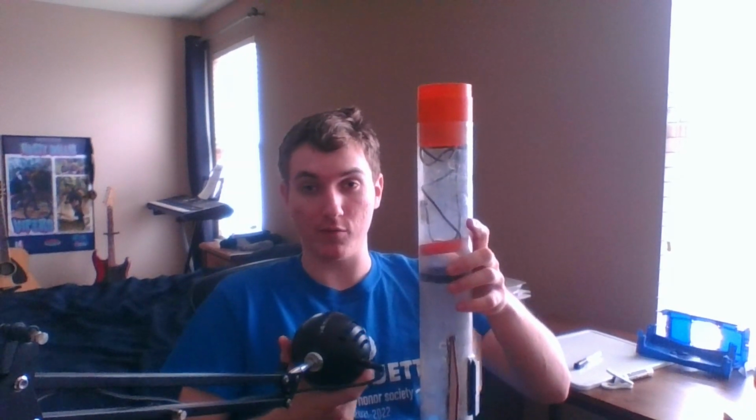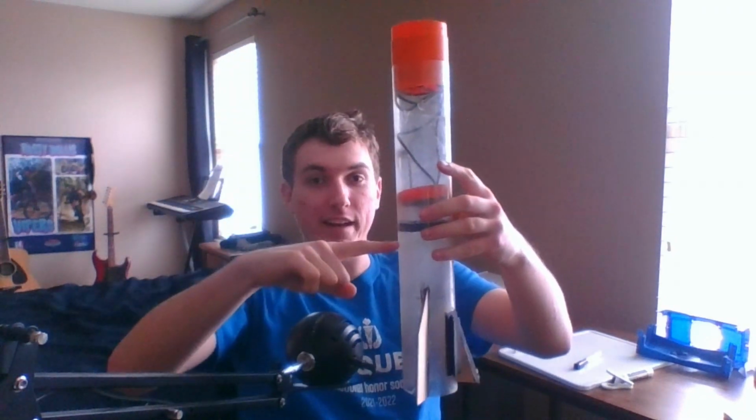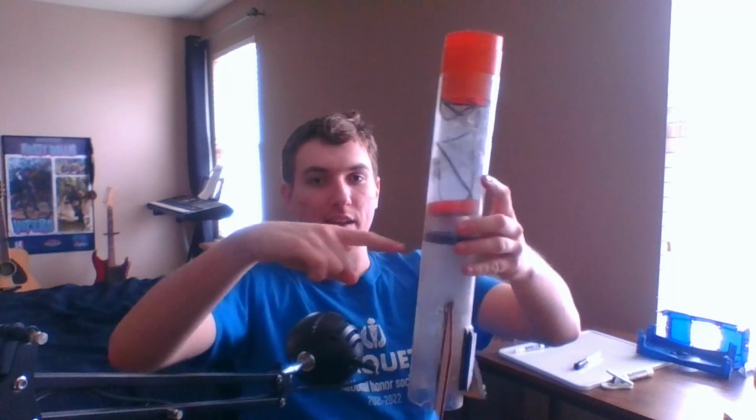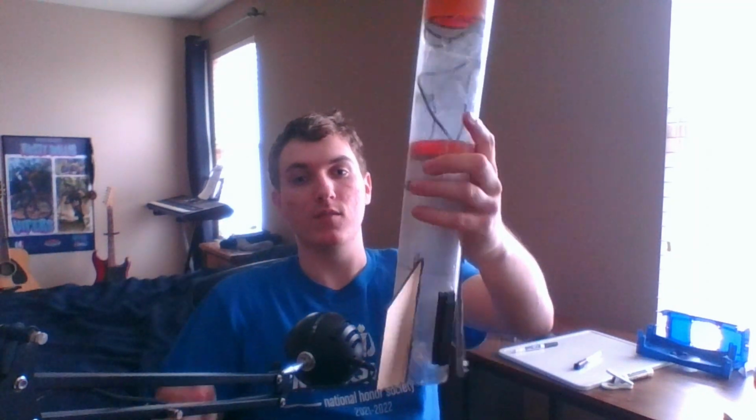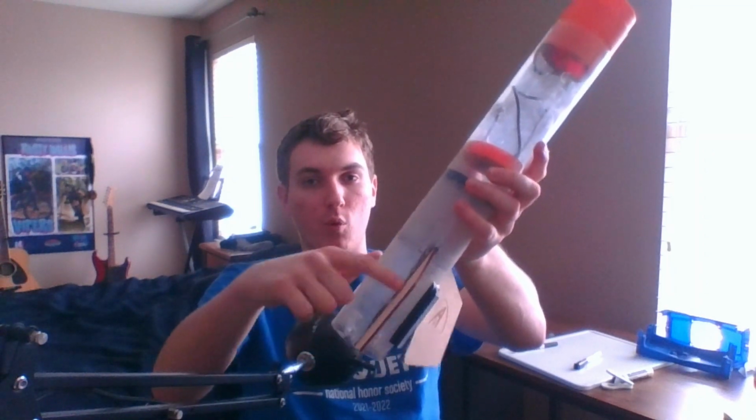This explanation is a lot easier when you have a rocket in hand than it is with a 2D drawing. So I'm just going to explain it real quick. So let's say we have a rocket here. Eventually some amount of wind or some other horizontal force is going to hit the rocket. This will cause it to rotate around the center of mass, which on this rocket would be about right here. Imagine the rocket's a lot taller. The wind is going to hit it, and it's going to rotate from this side. Let's say it just rotates this way, okay? What's going to happen is this is going to cause the fin to become more exposed.